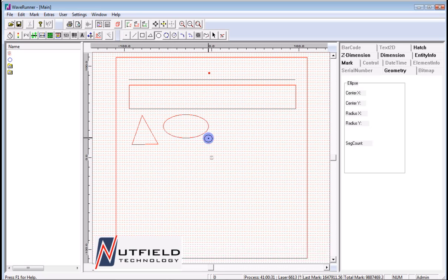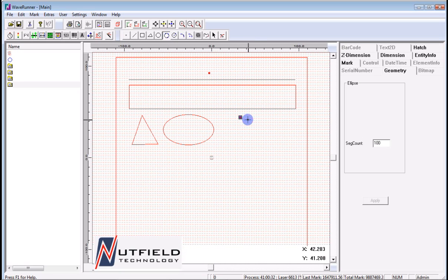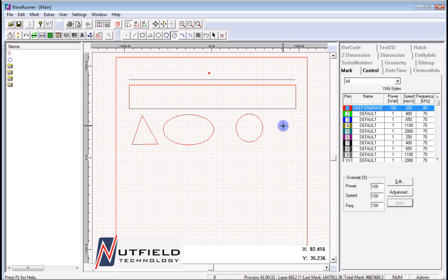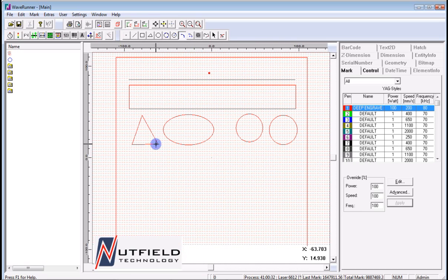The Circle, 3 points tool, like the Triangle tool, is a left-click the mouse at 3 separate positions to form the circle. Circle, center radius is a 2-click operation. The first is the center of the circle, the second is the radius of the circle. The Arc tools behave just as the Circle tools do.